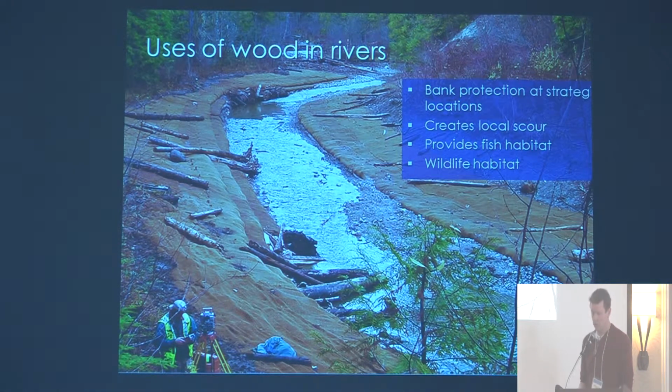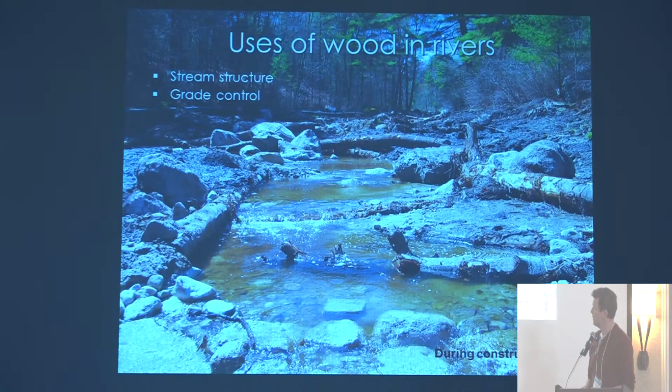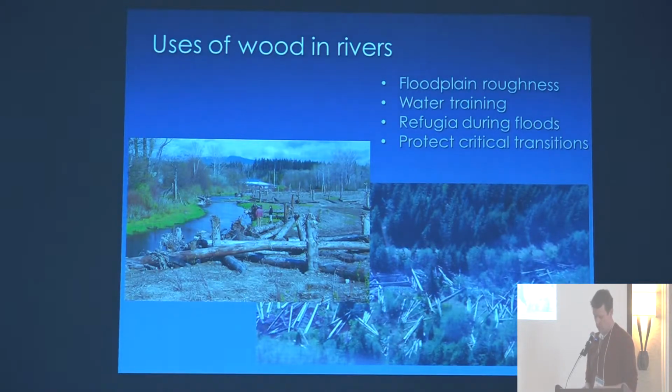What can you do with wood? Well, you can do a lot. You can stabilize banks in strategic places like in this project here, creating local scour as well and fish habitat. Oftentimes the benefits are combined. You can create scour pools. You can use wood as grade control and as channel boundaries, or at least temporary channel boundaries, especially in smaller projects.